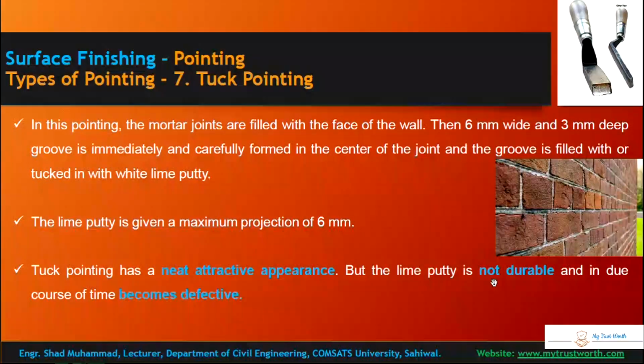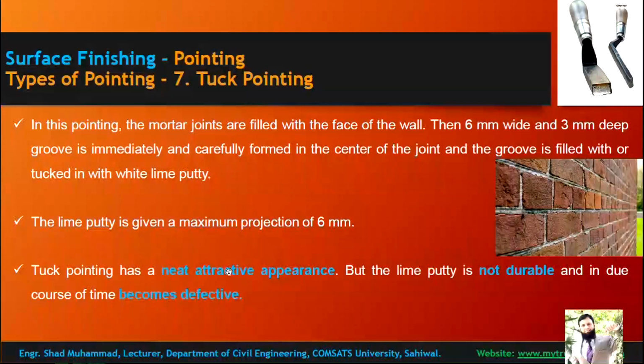Anyhow, if you use cement putty, that will also not be durable. One thing is this, that you do not have good bonding with this groove pointing. Second weakness is this, that it is protruded outwards. So another defect.